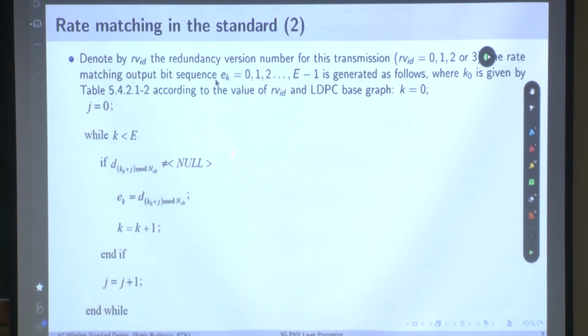If you hit the null bits, the input index will be different from the output index, because you have to skip those input bits, the ones written in the rate matching buffer. So what is this rate matching module doing? It is reading from the circular buffer and writing into another buffer denoted as E. It reads from a larger buffer and writes into a smaller buffer whose length is E. Do we understand this? That's how it is implemented.